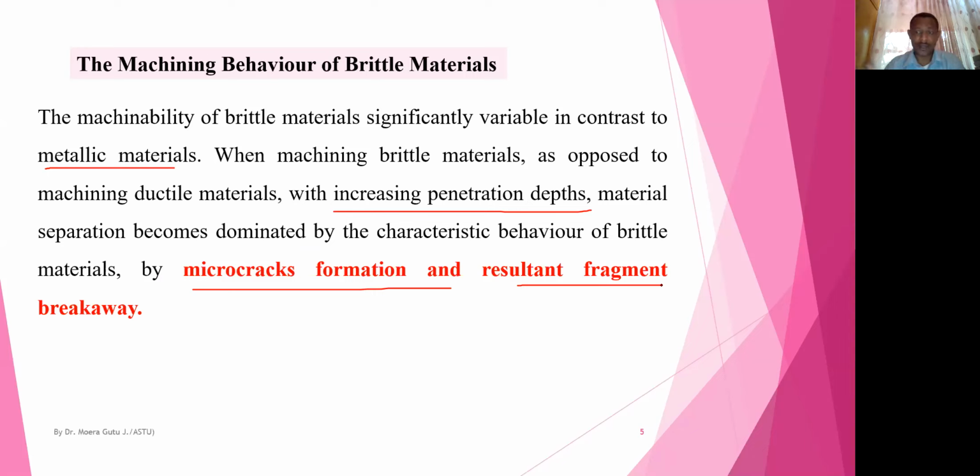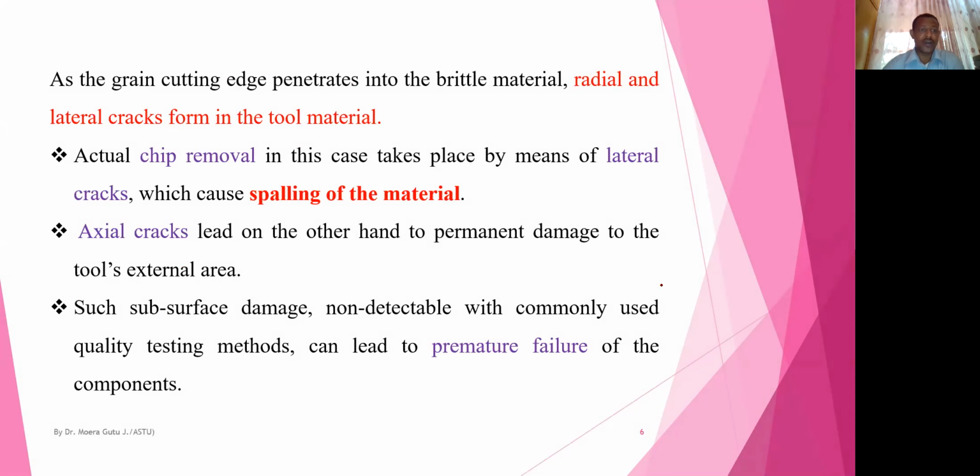So we have to approach machining the hard materials in such a way that the science and the features to apply to the cutting tools should be based on research. As the grain cutting edge penetrates into the brittle materials, radial and lateral cracks form in the tool material.